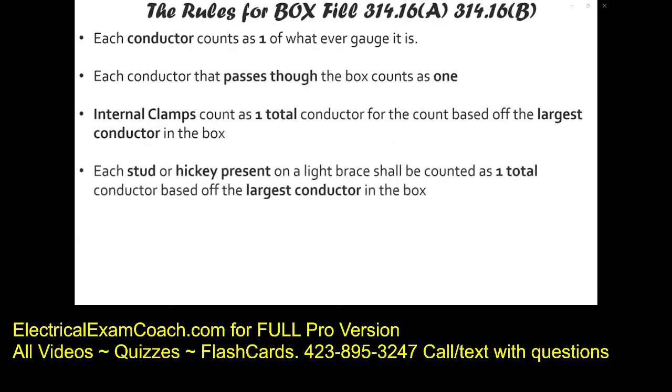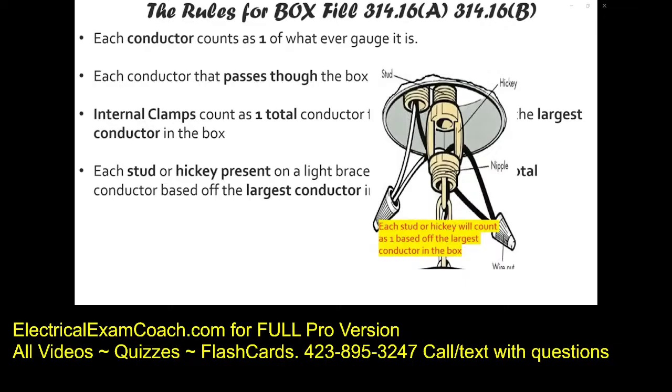Next, each stud or hickey that is present in the box shall count as 1 total based off the largest conductor that's in the box. Now, these are really old words, probably from the 30s if I had to imagine, but they still use them on examinations today. And this is what we're talking about. Imagine that we're hanging a chandelier. This we would call the stud or the nipple. Or, this would be a nipple, but they're calling this the stud and this a hickey. And they still use this terminology on exams today, so you definitely need to understand.